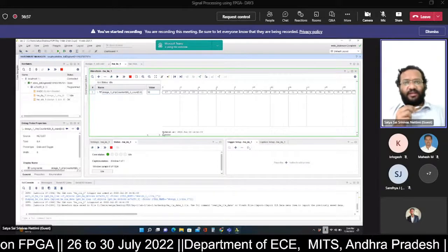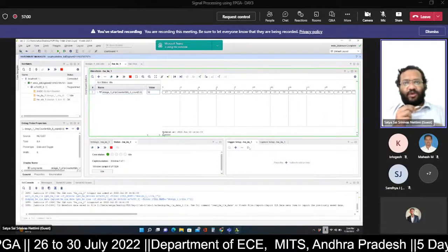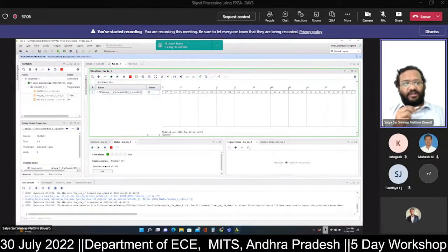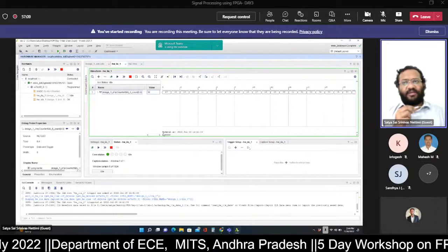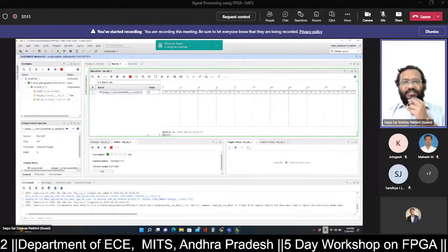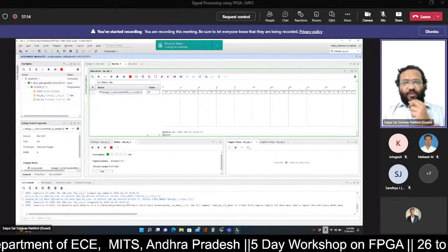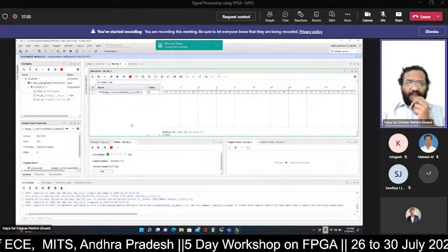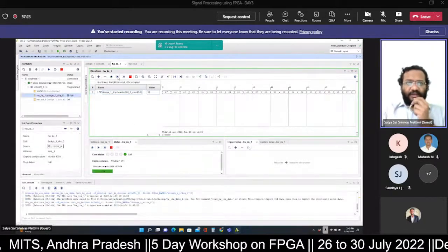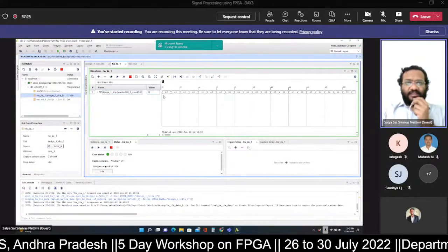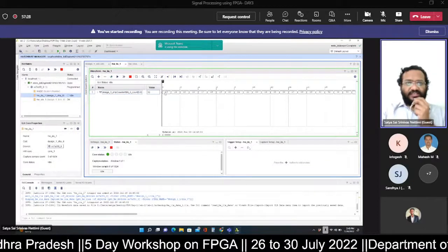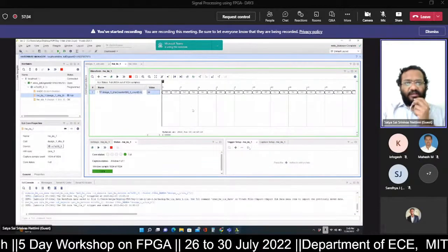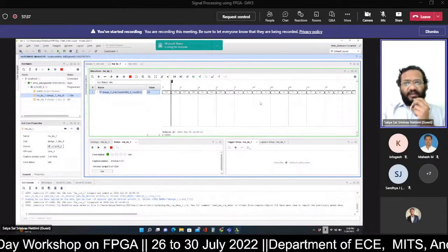Whenever you run the trigger, the captured output, whatever is there inside the memory, is passed serially through the data cable to the host computer, and from this you are able to visualize the data that is captured. You can also set up the trigger settings. I didn't give any settings over here. I just ran the trigger randomly. That's why you can see sometimes the starting sample value is 13, and sometimes the starting sample is 38 now. Again, if I run the trigger, the starting sample is 57, like that.